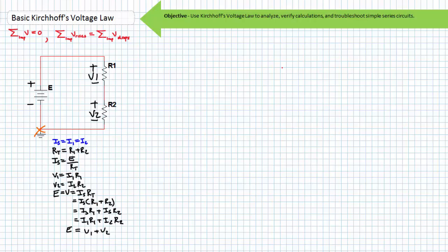First, if the circuit has a ground or a point of reference, start here. To start any other place is dumb. Second, if the circuit has a single source, or a single source that clearly overwhelms other sources, we'll get to that one in a little bit, travel in the direction of induced conventional current. To travel in any other direction would be hard. Our example circuit has a ground reference and clearly induces current in the clockwise direction. This is the smart place to start, and this is the easy way to go.